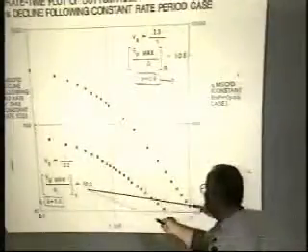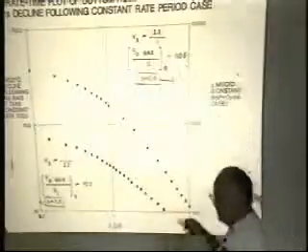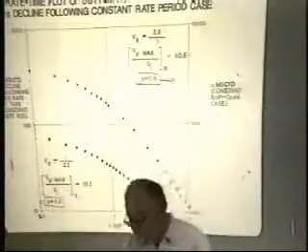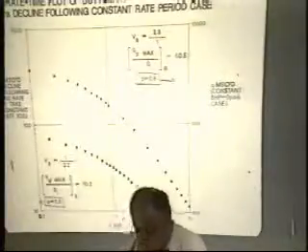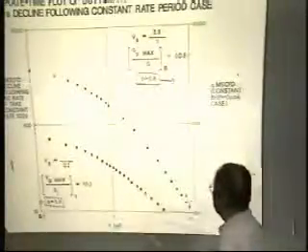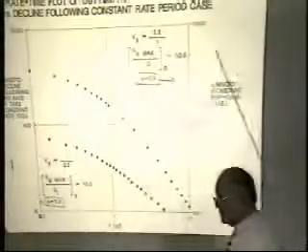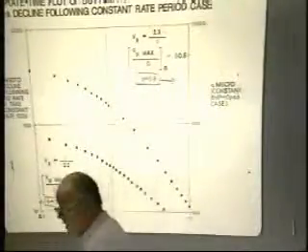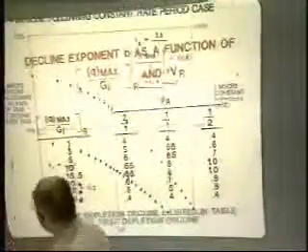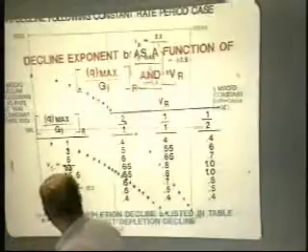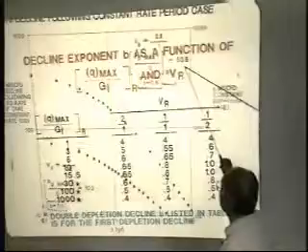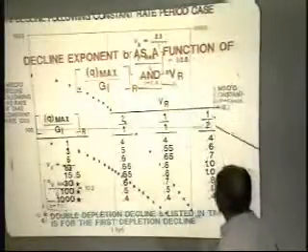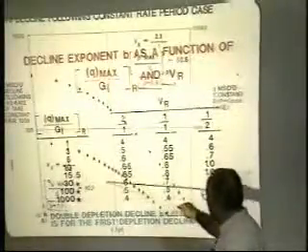With a Qmax over G sub I from the model here of 10, over here it's 50. If you go to the table, now also recognize that the B value here is 1. Over here it's 0.6. If you go to the table, in case I have to refer to it, the Qmax over G sub I of 50, the volume ratio 2 to 1, so I'll come here to 2 to 1.